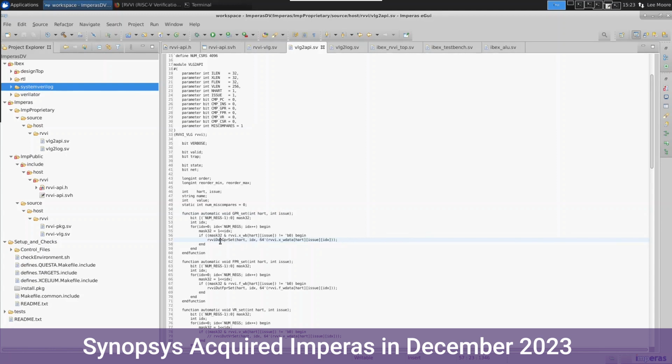So that passes it automatically across for evaluation later when we tell the reference within the ImperasDV environment to say, okay, we've just executed an instruction or a sequence of instructions here. Please do the same on your side and tell us whether or not we have a difference in terms of the computation and the internal state at the end of the retirement.